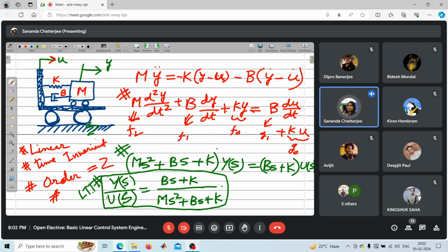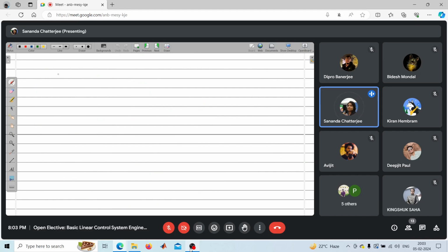So therefore, if we take the displacement and velocity as the two states, and we try to represent the first derivative of the states in such a way, say this is our y here. If I want to represent the system in such a form that the state, that is the energy stored in k, depends on the variable x1, and the energy stored in the mass depends on the variable x2. So I'll try to write the system equation with the help of